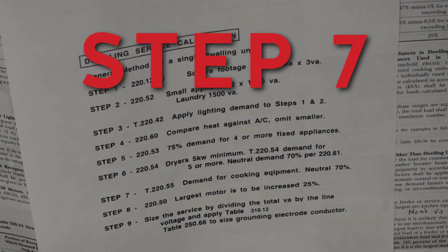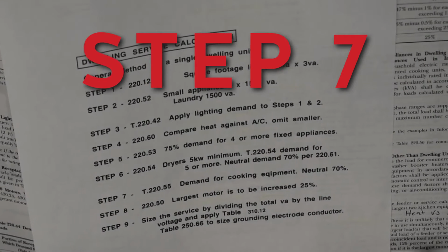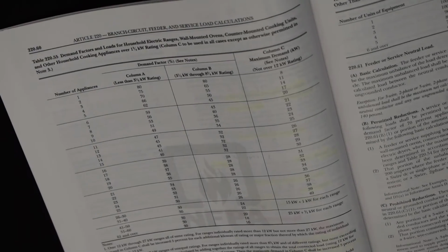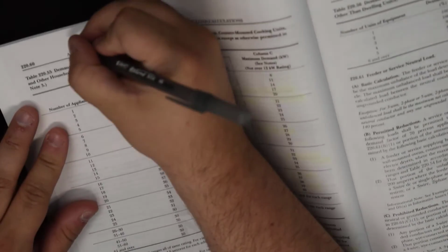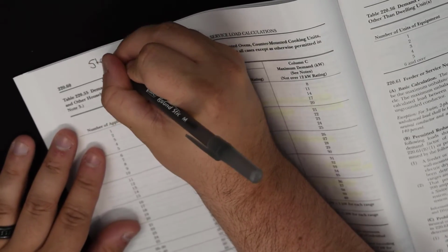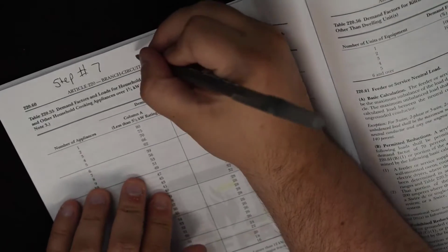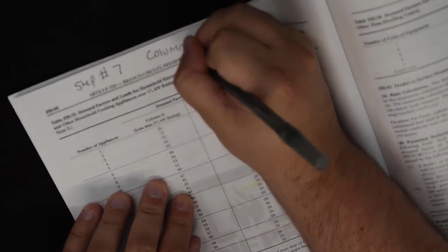We're going to table 220.55. It says demand for cooking equipment, and it also tells us that the neutral is 70%, just like it is on the dryer. So table 220.55 takes up a whole page. Go ahead and write at the very top of the page step number 7. And then after you write step number 7, write column C. And we'll talk about why we wrote column C up there in just a moment.